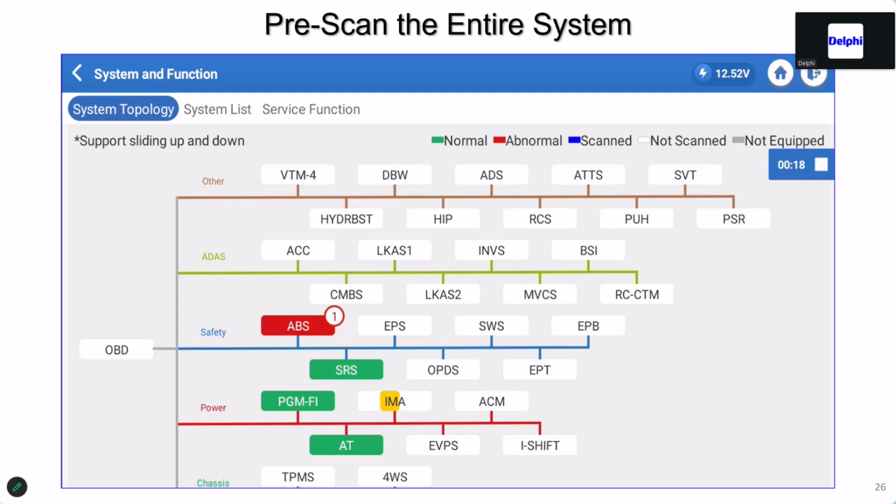It was another module, ABS issue, fuel pump control module on a Mercedes that wasn't coded, that was keeping the O2 and the O2 heater from running. I just had one the other day, and I'm going to show this in a slide coming up. It was a hood latch. The hood latch was reporting to the PCM, and that was considered an emission issue because the hood was open and the vehicle, they couldn't look at it as running, so they wouldn't run the test. And that's the one I'm finishing up today.